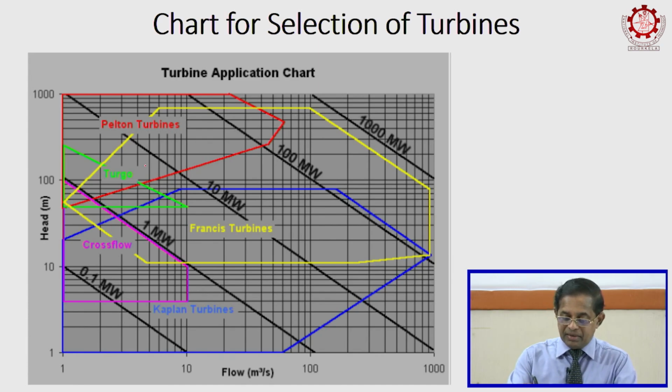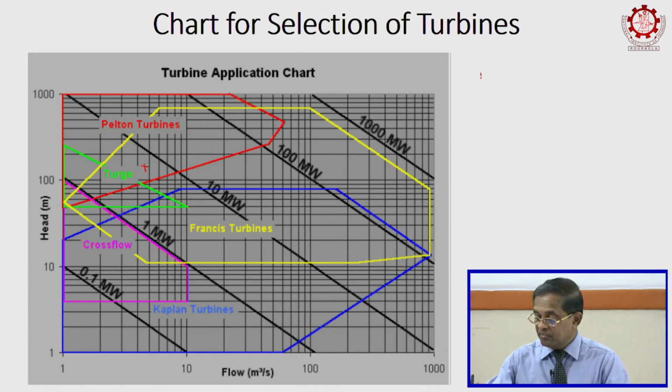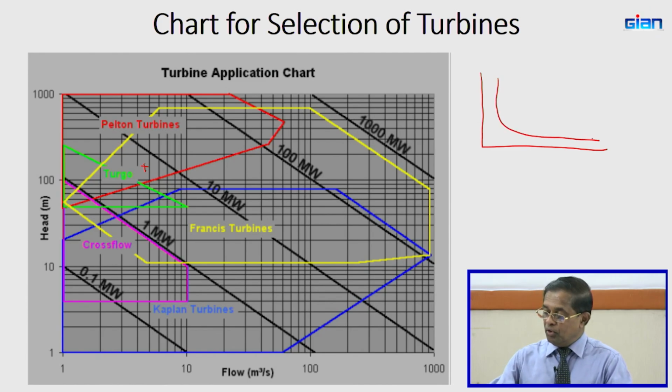But you have the same multi options. If you are here, you have the option for going for Pelton or Francis, both, right. Then you can take a decision depending upon your flow. If your flow is like this, then your low flow conditions are less. Low flow conditions you can see, but mostly your flow is high flows, right. Then in that case you can use even a Francis machine, right.